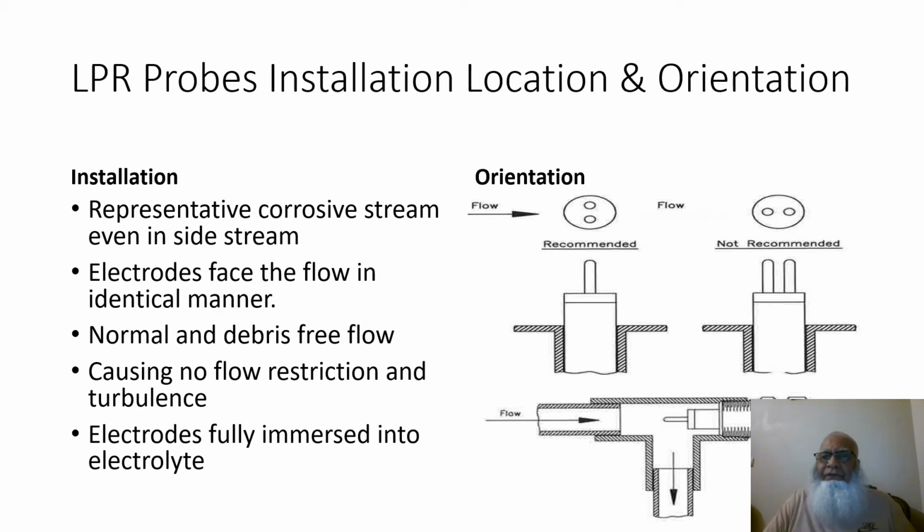Installing the electrodes parallel to the fluid flow is not recommended. This can also be installed as a side stream, or from the side, as shown in the lower diagram on the right side of the slide.